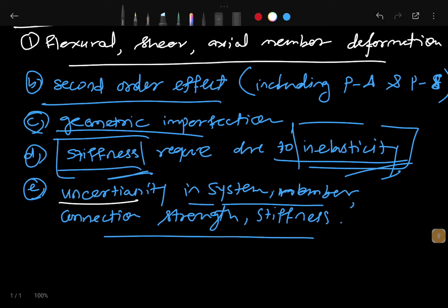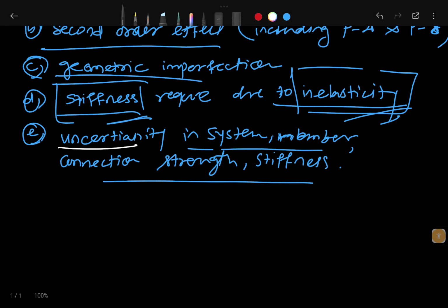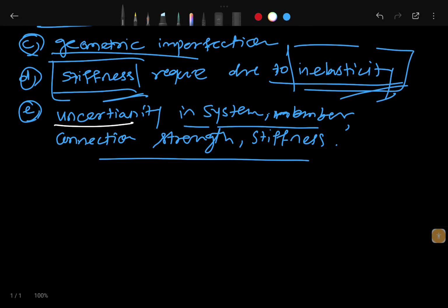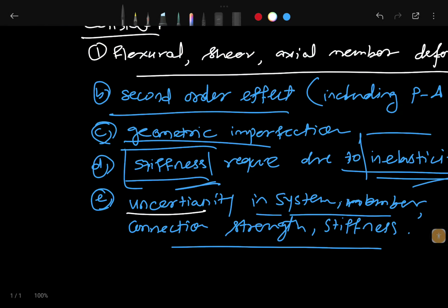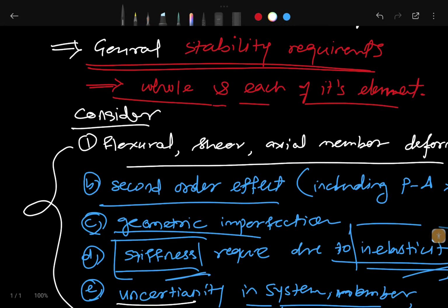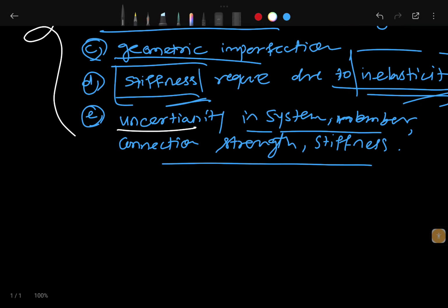All load-dependent effects shall be calculated at the level of loading corresponding to LRFD. In LRFD, the load combination is 1.6 times the ASD load combination. Any rational method of design for stability that considers all the listed effects is permitted. These effects are all included when we design for general stability of the structure. So our first point is complete.